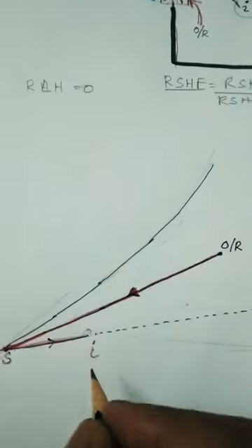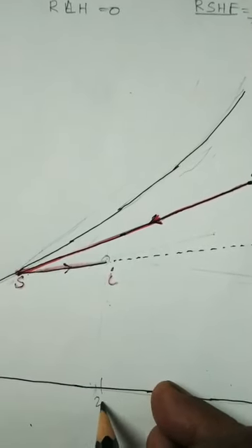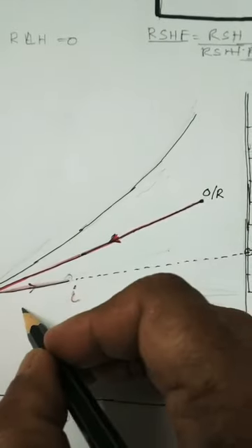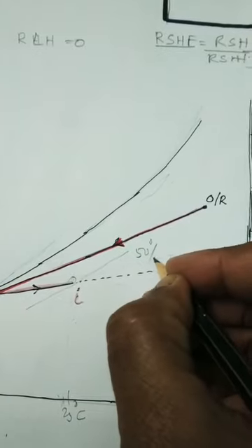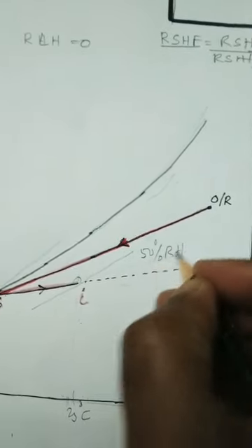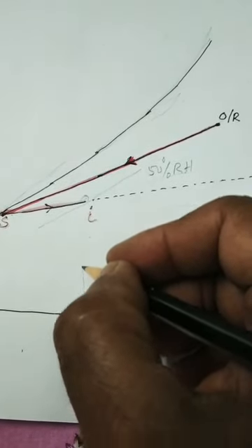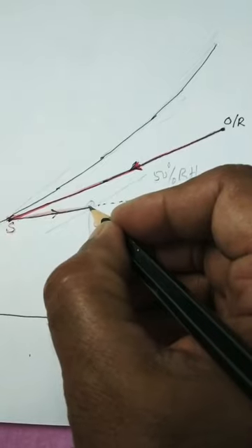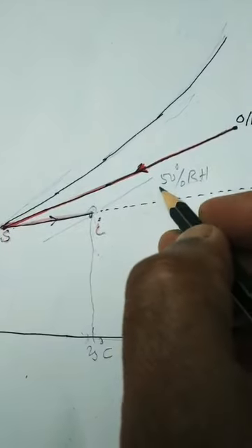If you take that value without looking at what the problem is, you just take 25 degrees centigrade dry bulb temperature, and you can say this is a line which is having 50% RH. Then you take a line at 25 degrees centigrade, and on 50% RH you will see that this is a point which is having what?